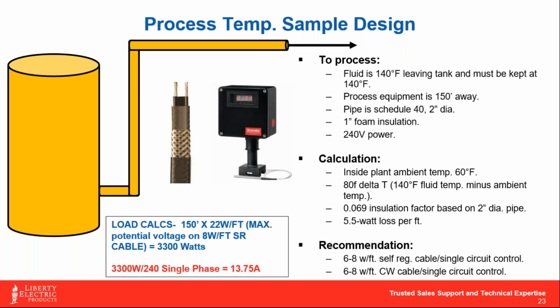So I'm going to run a number 10, let's say, out to my thermostat, and come right out of the thermostat box with the heat cable on the pipe, and away we go.